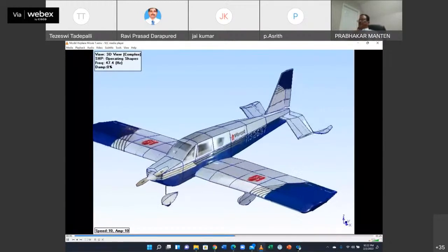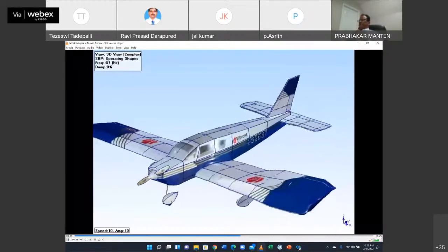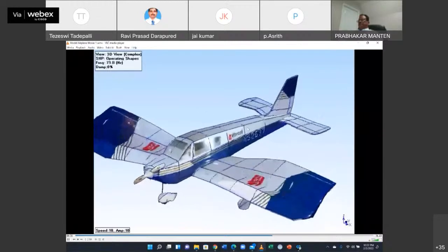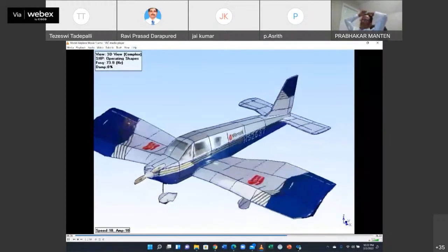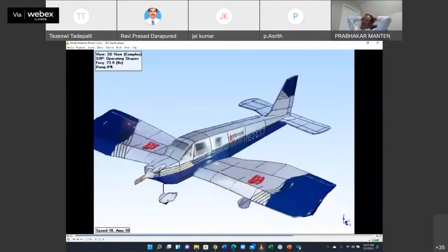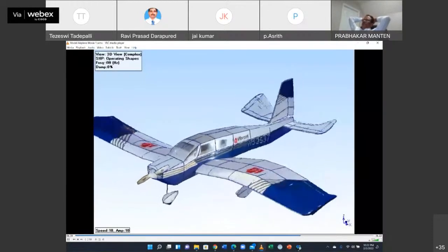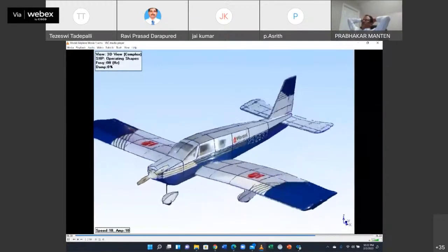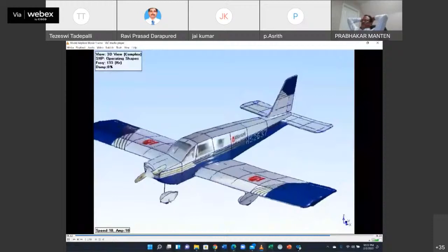Fantastic job with triaxial accelerometers, because there are some out of plane movements. And this is again the wing, with the forcing frequency of the flying coinciding with this twisting mode frequency at 67 hertz. That's how the whole airplane will be going back and forth. If the aircraft pilot stopped the speed of that engine at that RPM while you are flying in it, you would be scared to death, right? And this is a coupled mode of the second bending and twisting.